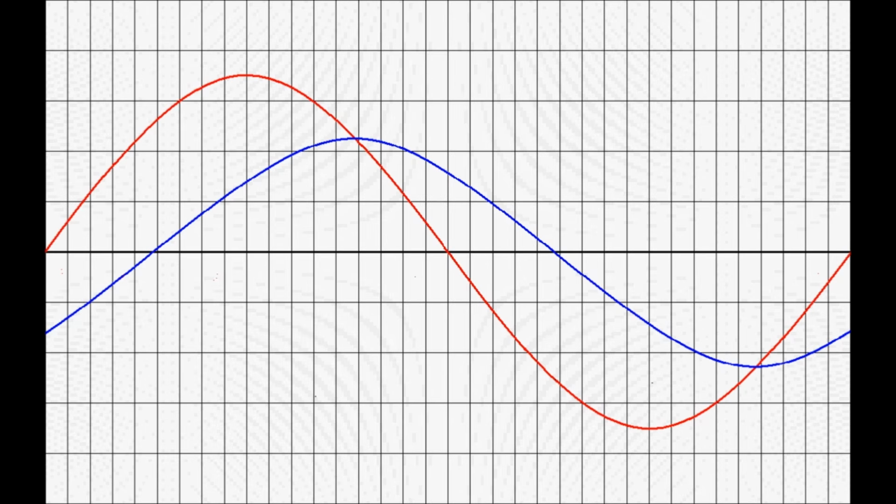If we reduce the resistance or the capacitance, the capacitor will charge faster and reach a higher peak voltage, but the capacitor voltage will still cross the source voltage at its peak. It has to. After this point, the source voltage is lower than the capacitor voltage and the capacitor will begin to discharge.